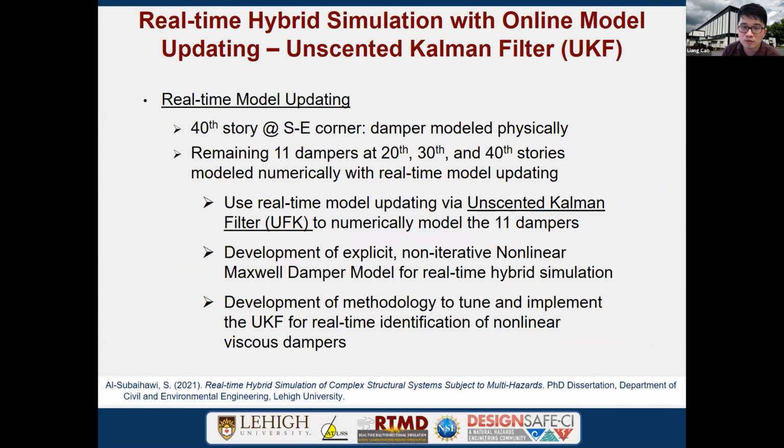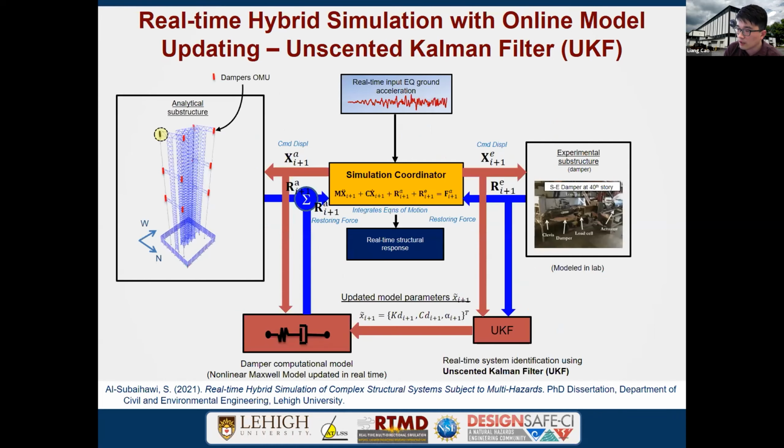And to do the real-time model updating, we're using unscented Kalman filters to numerically update the dynamic parameters in the numerical damping. Also, because for the nonlinear viscous damper we have to model this as explicit, everywhere everything is explicit.